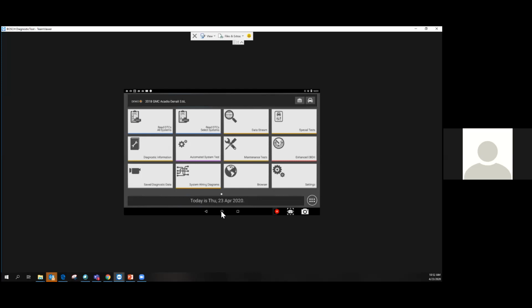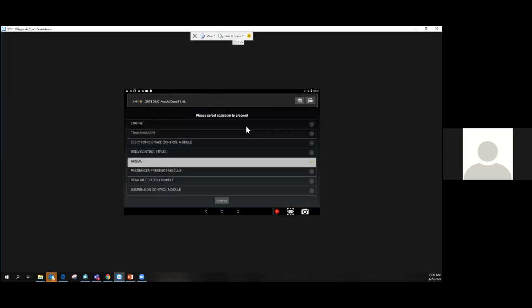Thank you. Okay. And then, we kind of mentioned post-scan, already discussed that, when we should do it, why we should do it. We've got to document. Paper trails are very important. When codes don't clear, what we do to research them. Like I can do a deeper dive. I can go on all day here. I can show you how to get into data streaming, right? I want to watch my values in my airbag. It's not just for calibrations and activations.